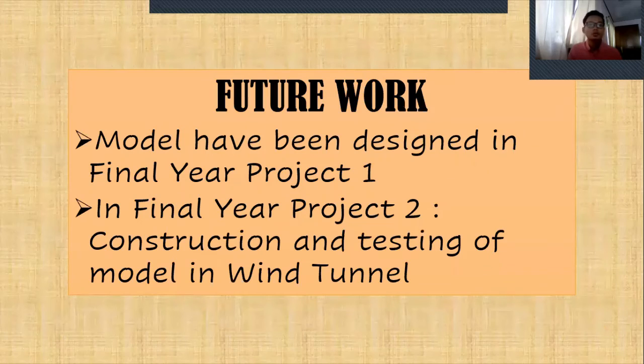For the future work, the model has been designed in Final Project 1. So in Final Project 2, there will be the construction and testing of the model in the wind tunnel, experimenting on the distribution of wind pressure coefficient on the model in order to determine the wind loading on the residential house.